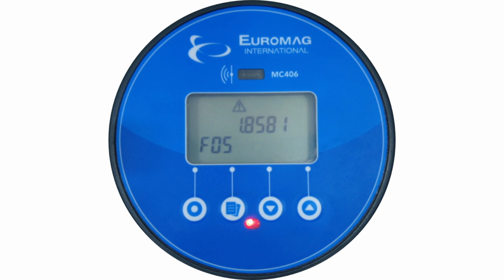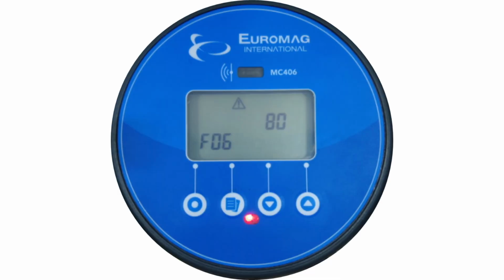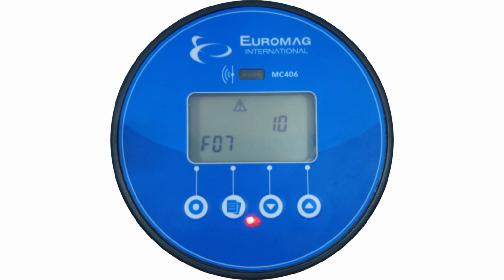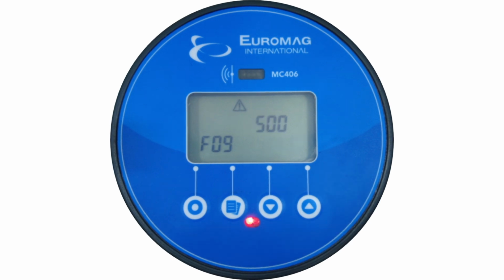Function number 5 is another setting that will only need to be changed upon replacing or upgrading an existing converter. Function number 6 is used to set the diameter of the sensor body itself. The nominal sensor diameter in millimeters is to be used. Functions number 7, number 8 and number 9 are used to program the pulse output parameters.